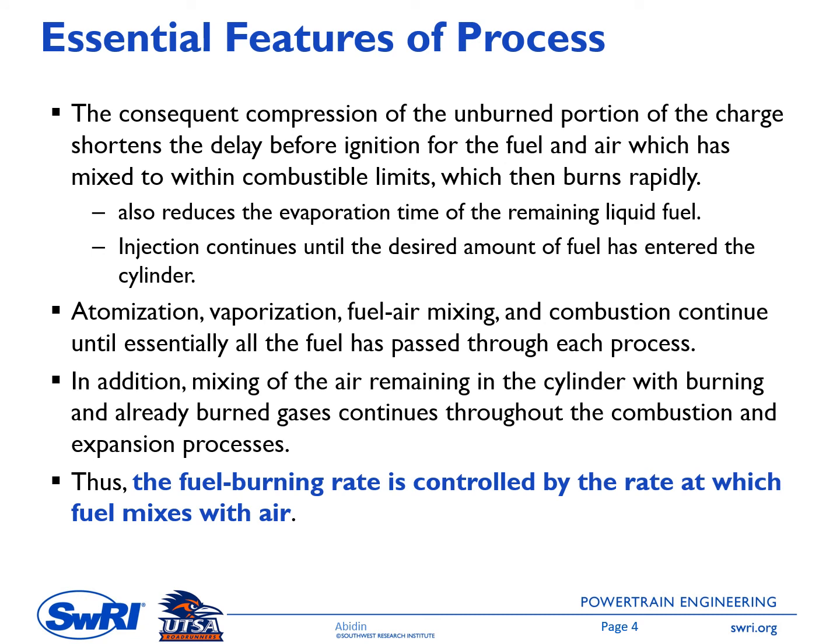So it will shorten the delay period. So this high temperature, high pressure also reduces the evaporation time of the remaining liquid fuel. So it means that the fuel that is injected later will have a shorter evaporation time. And then the injection will continue until the desired amount of the fuel has entered the cylinder. And you will see later on that in diesel combustion engine, the amount of the fuel is used to control the level of required load.